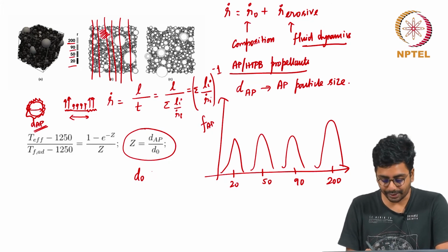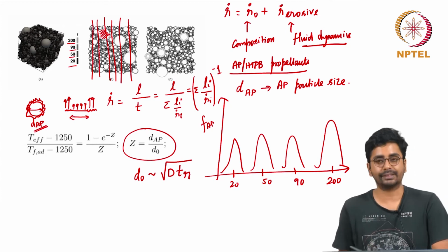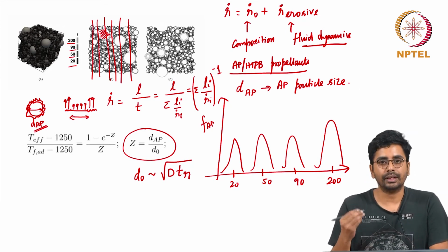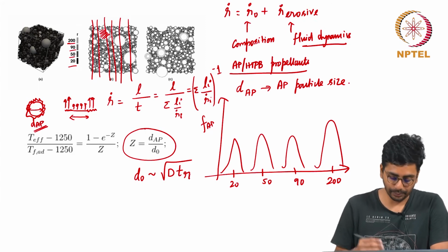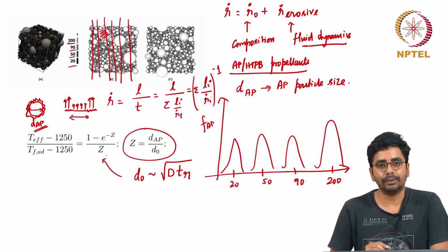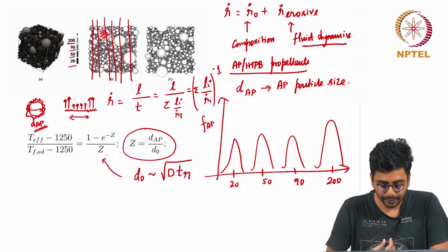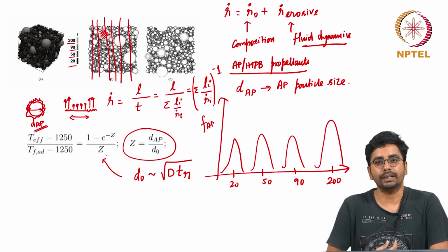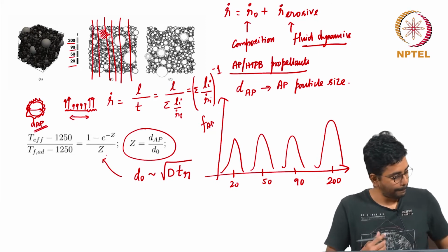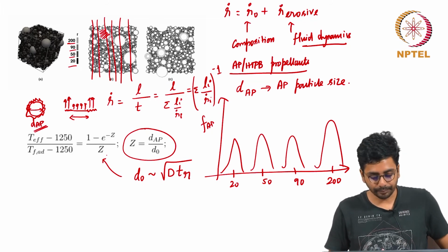If you go back and check, the equation for D0 is exactly this reaction controlled diffusion distance. This simple idea was encoded to calculate the burn rate of different particles that constitute the statistical particle path, and from that the burn rate of the propellant can be calculated. This is the crux of the heterogeneous quasi 1D model.